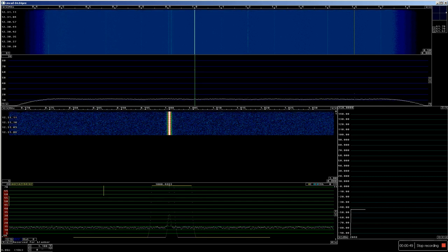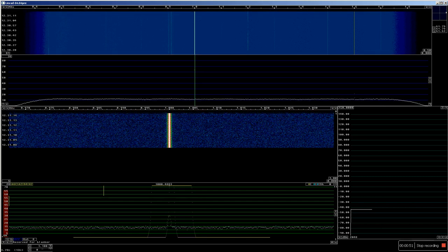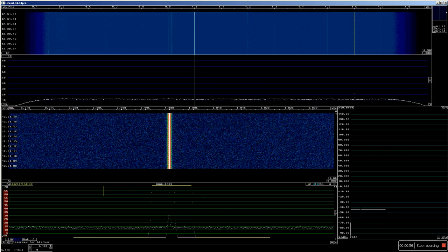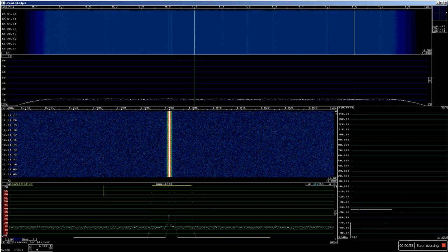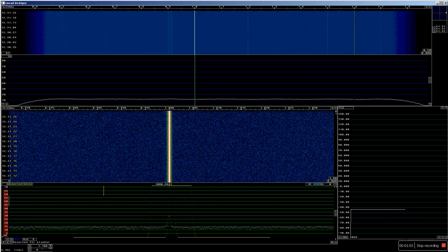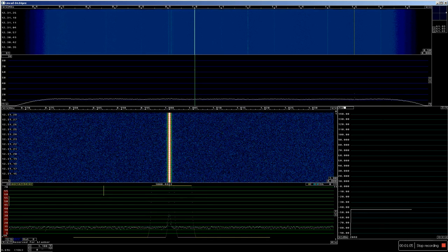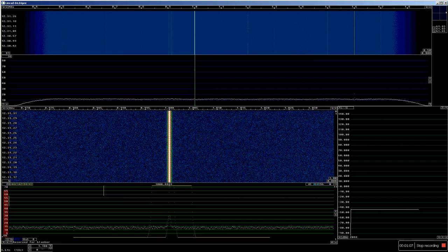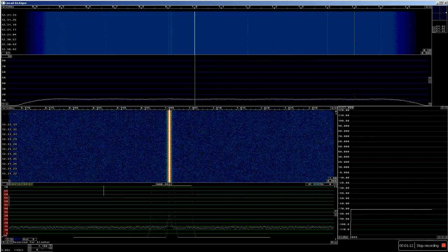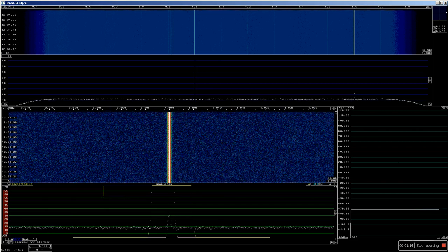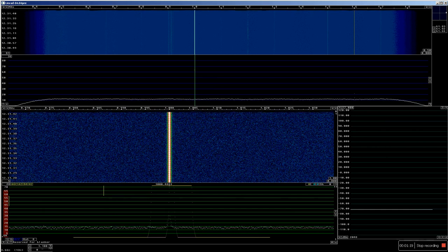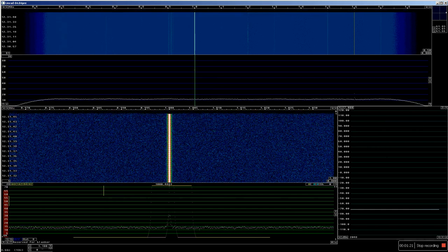and we can see it doesn't show what it should. It should show minus 70, but it shows something else, minus 43 or so. So I had to add 27, one or the other sign, I don't remember. It was the rate. Now it shows minus 70 dBm. So I have to take notes to transfer this to the recording.